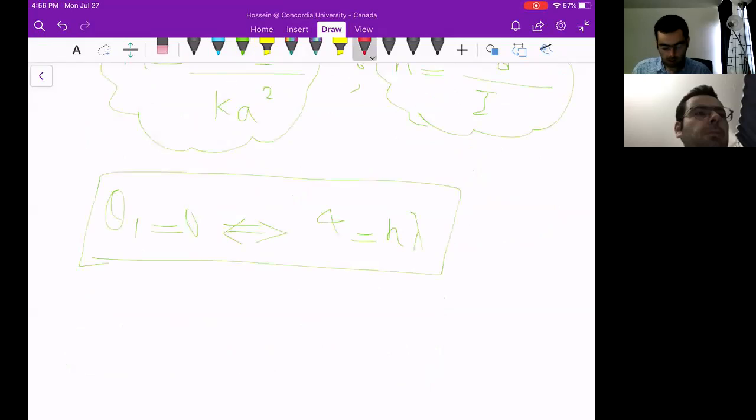Therefore, this is the mathematical translation of designing the absorber. We are just taking a look at the numerator of the response. So it basically satisfies the relation we used in the first part of today's introduction, K2 over M2.